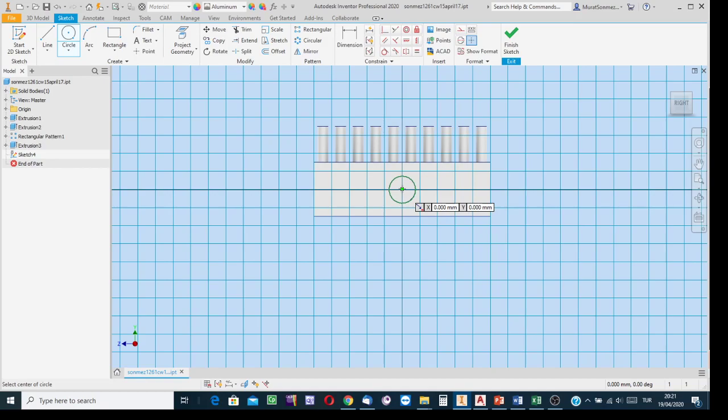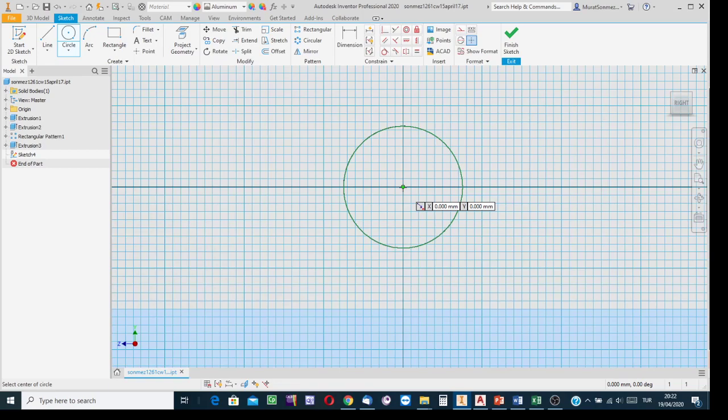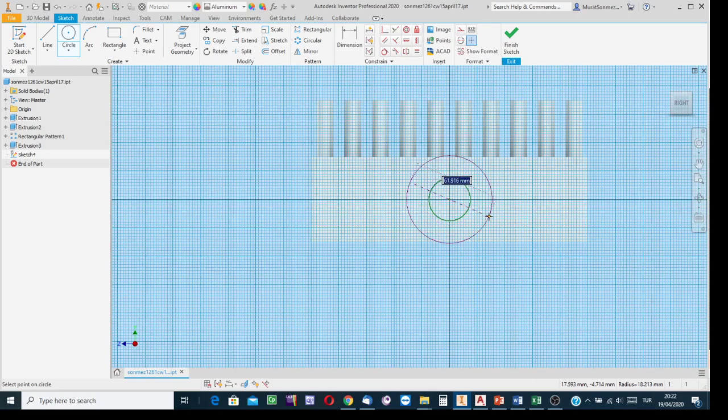I created the projection of the boundary of the tip surface, the flat surface of the cylinder. So in the sketch plane, the center is a characteristic point and it can be indicated. I brought the cursor to the vicinity of that point. You see there is a green ball, which means Inventor is ready for our indication.